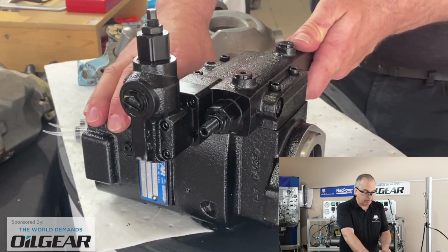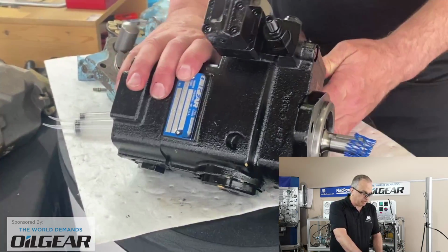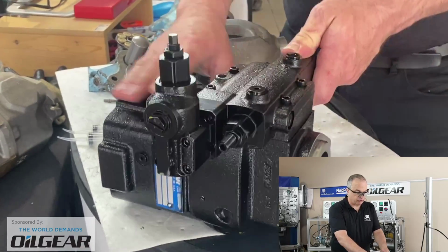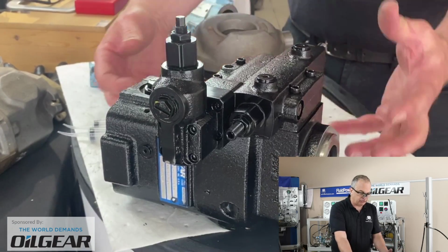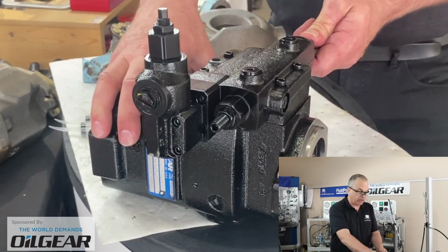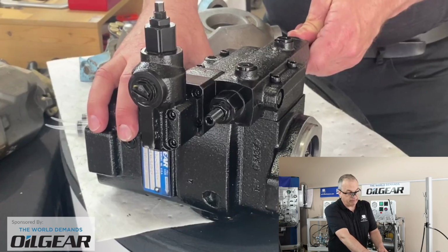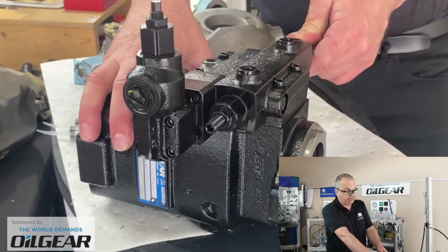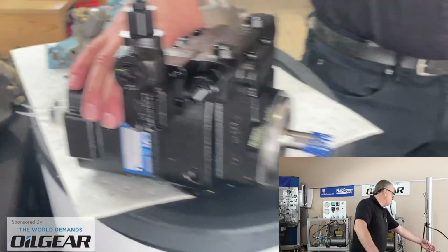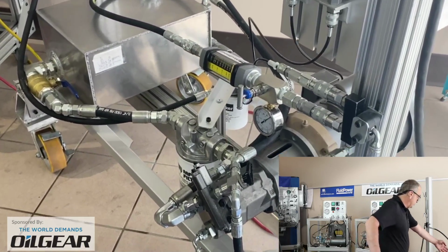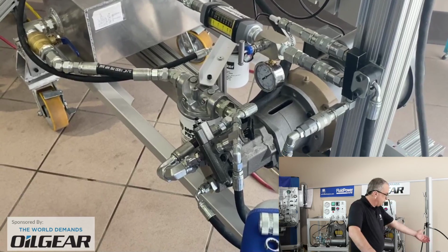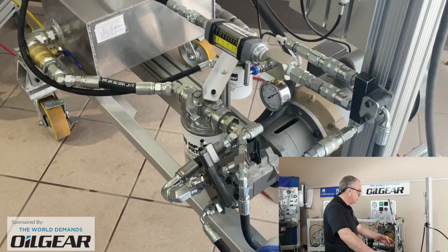And of course, I didn't mention earlier, these pumps can be rated for very different pressures. So this one has a very thick casing and a number of special places with bearing surfaces on the inside. This one is continuous run at 5,000 psi, intermittent up to 5,800, whereas the Rexroth A10, the one we've got anyway, is about a 3,600 psi nominal pressure, perhaps a bit over 4,000 for intermittent.